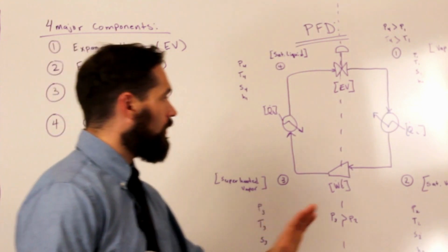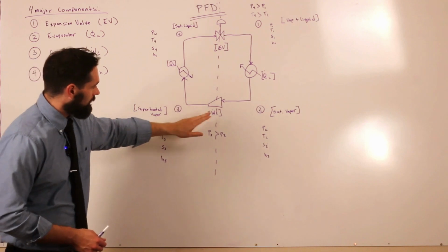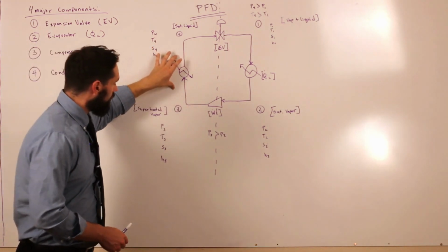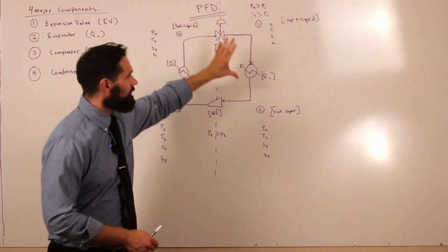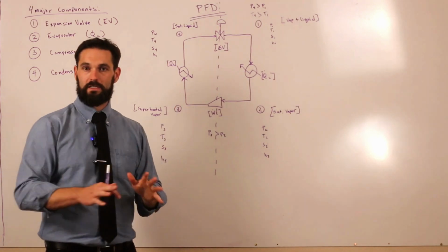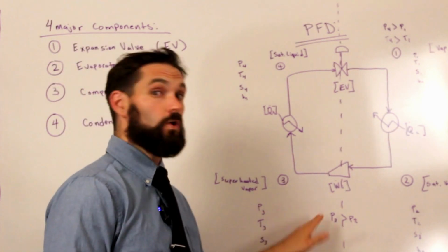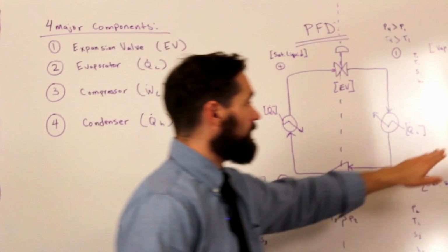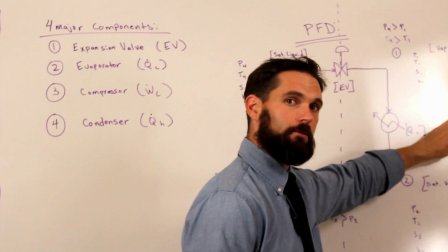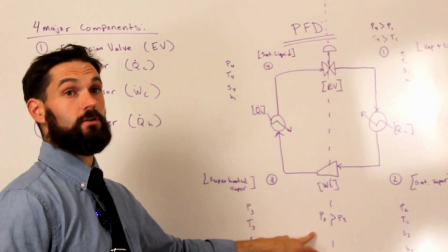Well, we could go through the whole detailed design, every intricate detail of the compressor, the piping, the heat exchanger, the valve, the other heat exchanger, and we could go through that whole detailed process and waste everybody's time to figure out that this isn't going to work. We're not going to save money because all the added production that we made in the reactor is going to be offset by the increased compressor cost.